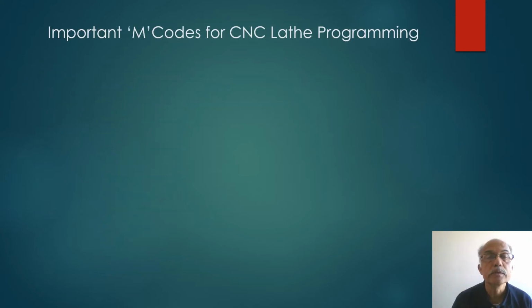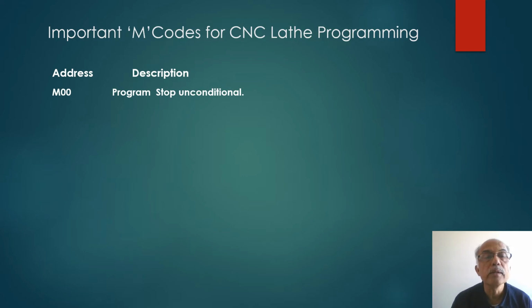Now we'll discuss important M codes for CNC Lathe programming for Fanuc OT Control. First is M00. This code denotes unconditional program stop. Here machine will stop and we can do some operation like inspection or deburring. So here program will stop.